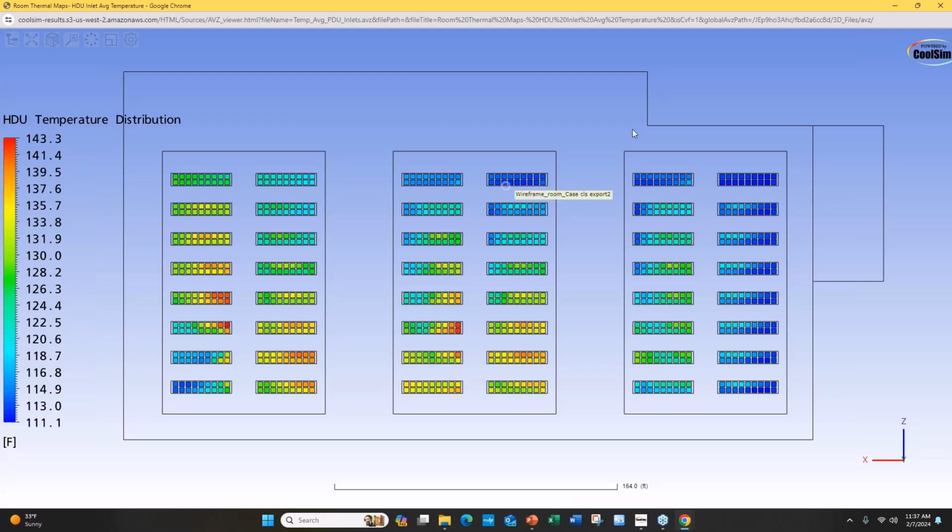So a couple questions coming in. Can the 3D path line be constrained to show only a section of the model? Yes, it can. What is the effect of the screen on those chillers with respect to the wind? The screen, you can adjust the percent area open on the baffles to represent percent area open on screens, so you can model that.